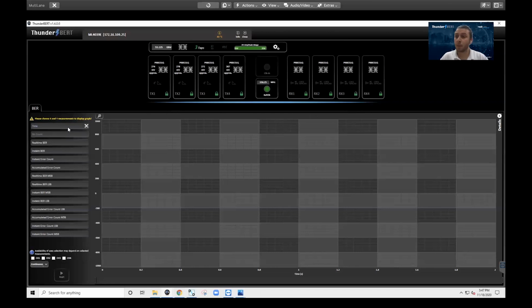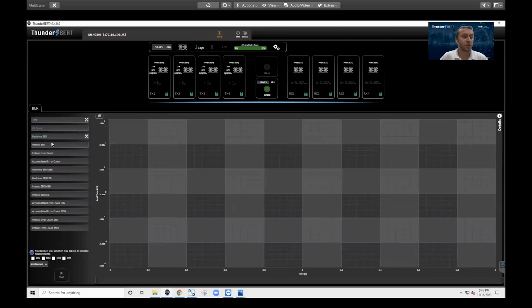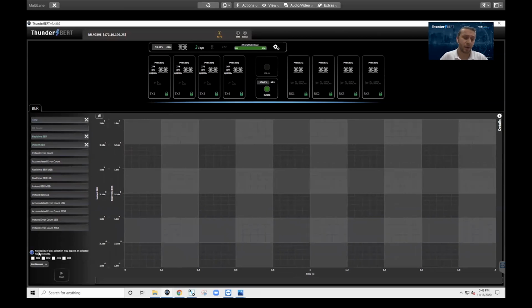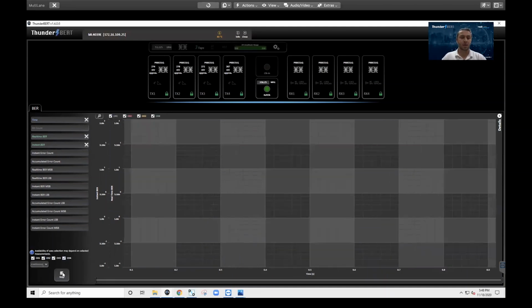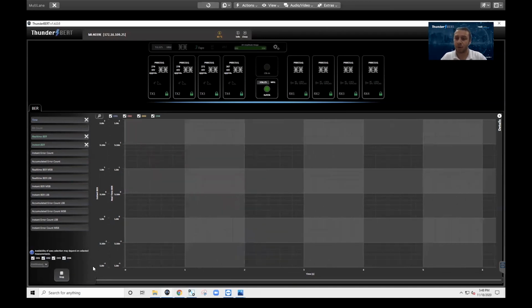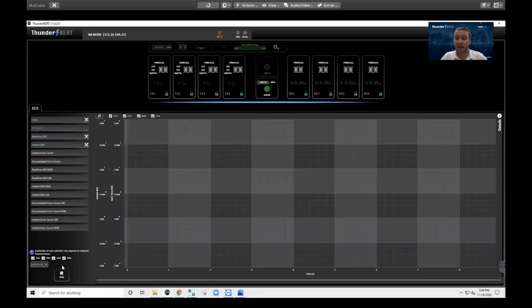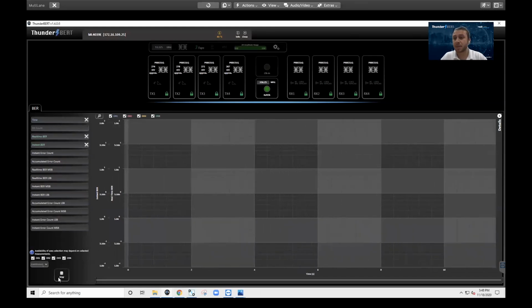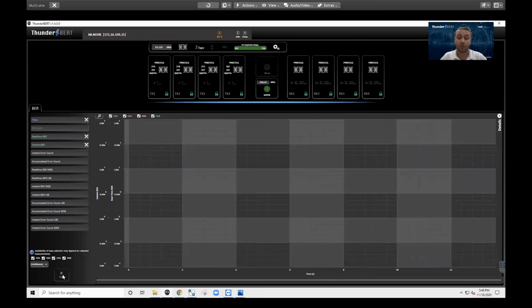So I'm going to go ahead and kickstart a bit error rate test. To start a bit error rate test on ThunderBERT, I select my x-axis. I'll go with time as my x-axis, and then I will select real time and instant BER. Then I will make sure I'm running a continuous test, and I will select the 4 channels to all run simultaneously. So I get that started, and you can see the graph updating, but you don't really see any activity on the graph right now. That's because I have configured the taps in an optimized setup to run error-free.